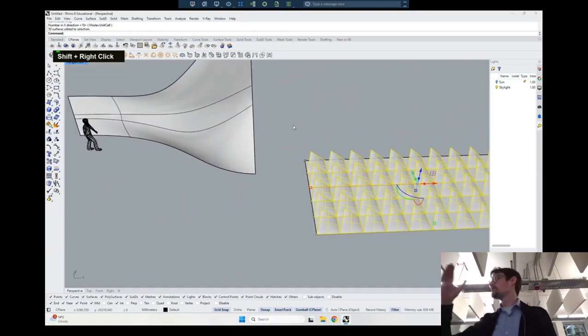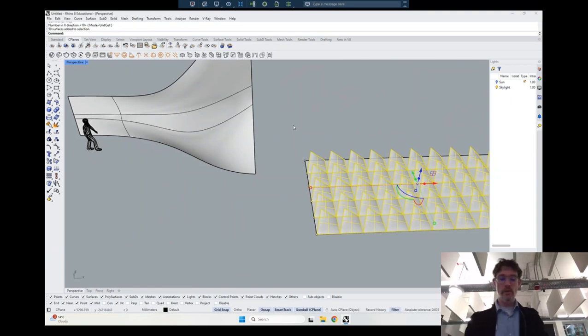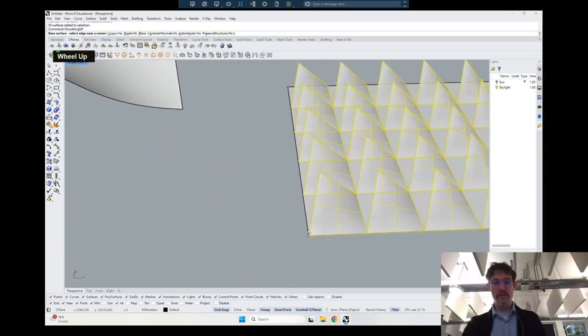And what I'm going to do is, I showed you this before. Someone had a question about putting text over a curved surface, and I used the command flow along surface. Do you remember that? Maybe you've got it written down in a note somewhere. I can do exactly the same thing. Flow along surface. And it says, choose a base surface. So I'll choose an edge near a corner. I'll choose this edge down here.